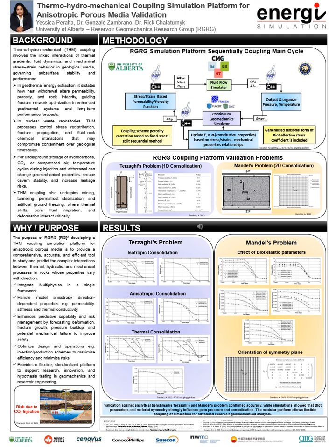For capturing this, we set different values for Poisson's ratio in the vertical and horizontal direction, while keeping Young's modulus equal in all orientations. So, as you can see in the plots, pressure against time and settlement against time, the numerical result for pore pressure dissipation and surface settlement show excellent agreement with the analytical solutions developed by Cui and co-authors in 1996. This confirms that our model can correctly simulate the influence of anisotropy, which is an important factor in real geological formations where layering and fractures strongly control fluid flow and deformations.